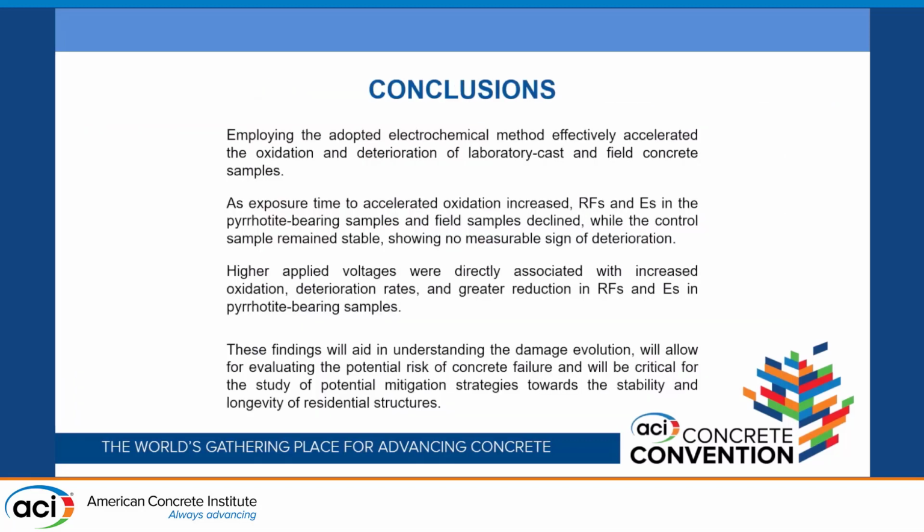So now, in conclusion, employing the adopted electrochemical method effectively accelerated the oxidation and deterioration of laboratory casts and also field samples, and those are shown in our results, some of the pictures I presented in the previous slides. As exposure time to accelerated oxidation increased, the resonance frequencies and the dynamic elastic moduli in the pyrrhotite-bearing samples and field samples declined, while the control sample remained stable, showing no measurable sign of deterioration.